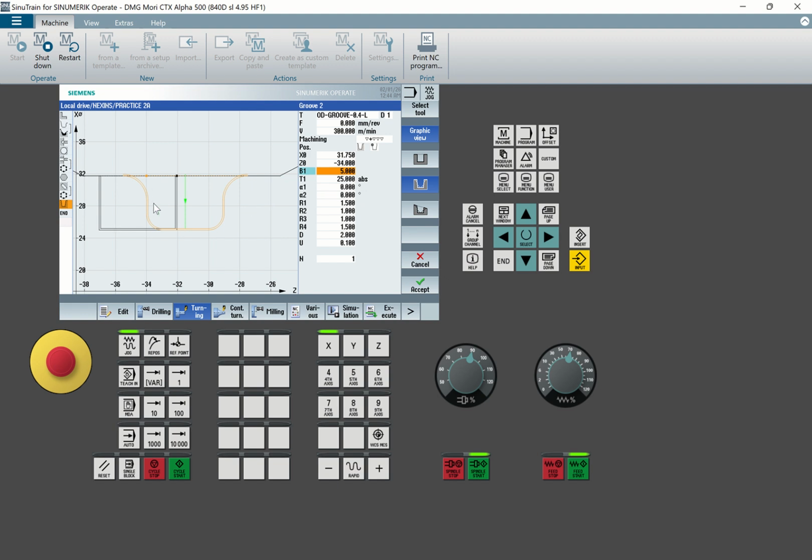I will remove the other one because I don't want to use that one. I can put a 1. I don't want to put chamfer. Let me put 0. Even this R3 can put 0. Let me put 0, 0, like that. So the first one, I want to put a chamfer of 1.5. And then the last one, a chamfer of 1.5. You can see, or a chamfer of 1 is okay, 1.5 is too big. Okay, you see this is what it has done.